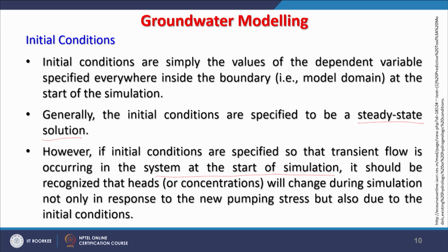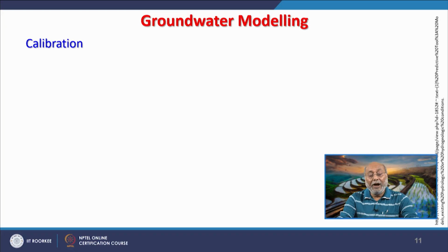So, these should be specified at the start of the solution, and it should be recognized that the head or concentration will change during simulation, because everywhere things are not constant, and not only in response to new pumping stress, but also due to initial conditions. Since initial conditions might change during the simulation, that kind of incorporation in the model also has to be done.